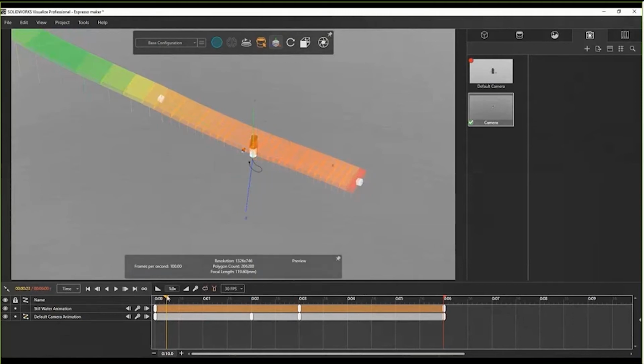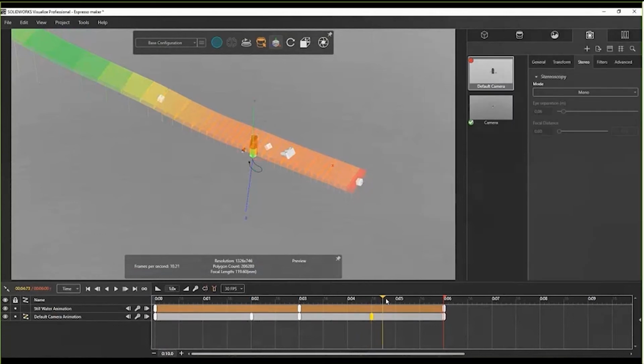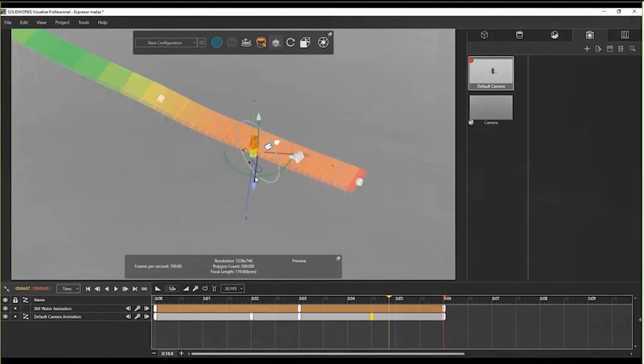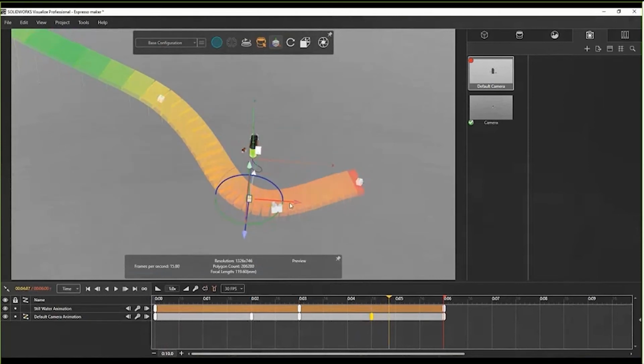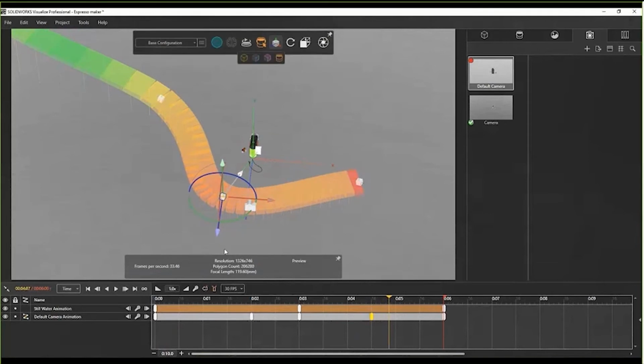And these little white boxes are those keyframes. So I can click on them, I can manipulate them, move them as you normally would any part that you have, and I can add another keyframe in here to get that placement where I want it to go, right? So if I click on it, we can bump this thing into the exact position we want it to be.